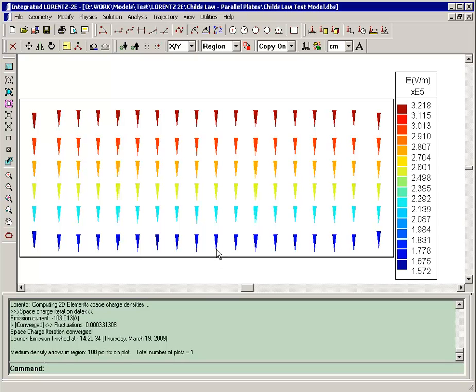And in fact, the criteria where you pinch off the beam is when there is enough charge present that the field is exactly zero right at the emission point. And as the rays are traveling more quickly, the charge in the beam is covering more space in the same amount of time, and therefore the charge density becomes lower, resulting in a higher electric field at those points.